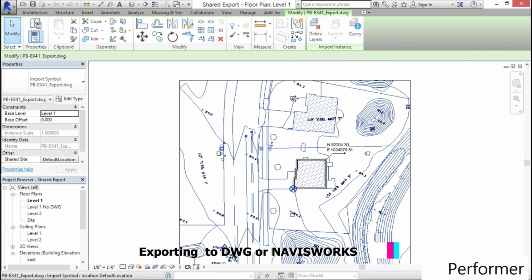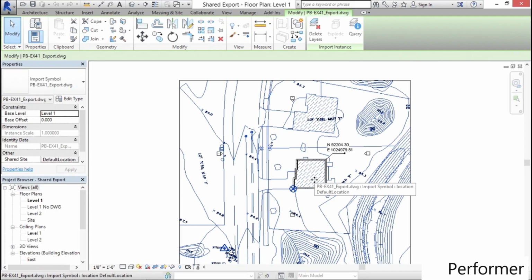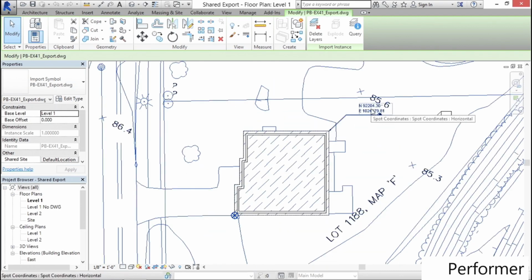And you can see the 4 elevation markers here that the project started with. And I centered in on that one house that we've been talking about in the last several movies. Then if I zoom in a little closer on that house, you can see that it is reporting the coordinates from the CAD file because I did the acquire coordinates. And what I've done is I've traced over it using some basic Revit geometry. So I've just got an outline of walls, and then I also put a roof on that object as well.